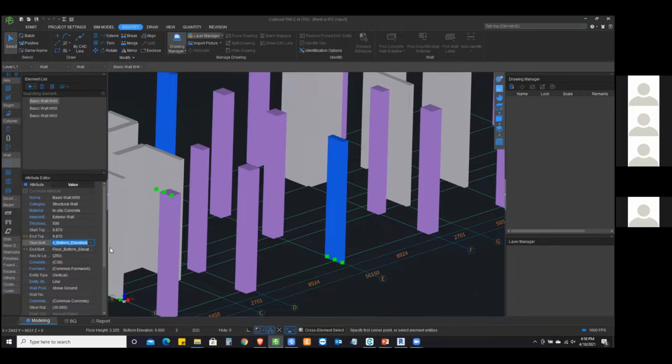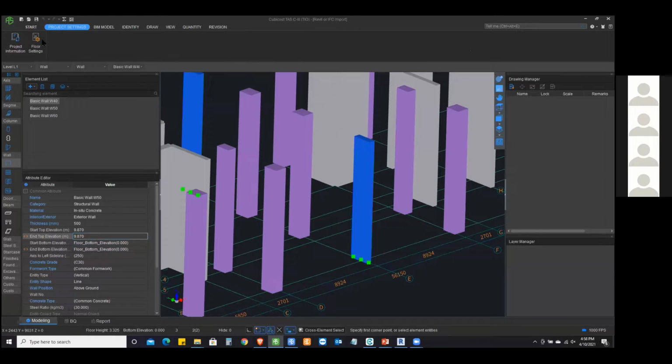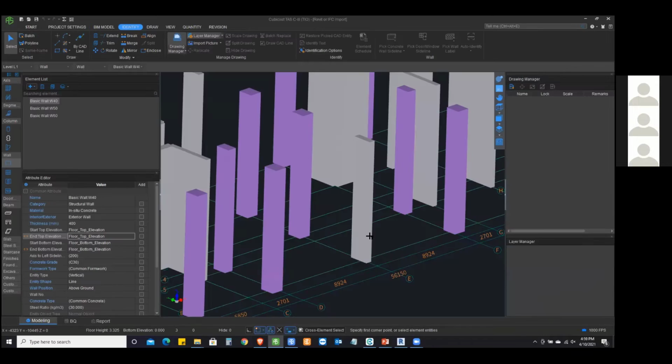Now, if you go to the details here, it's following the same thing. The top elevation is 9.87. Okay, now let's have a look at what's 9.87 here. So that is basically right here. I mean, it's going all the way to the top, just below the level 2, a little bit down from the level 2. So it is basically showing me that it went all the way from 002 up to the top level, which should not be the case in order to fit in the model. So this is how you get to see what is happening inside of that.